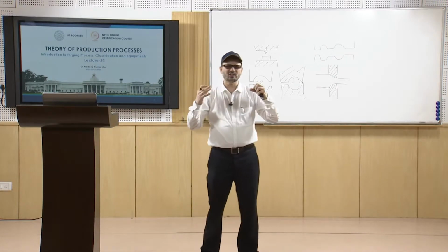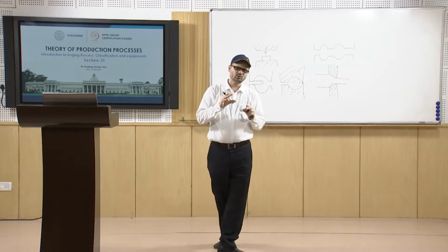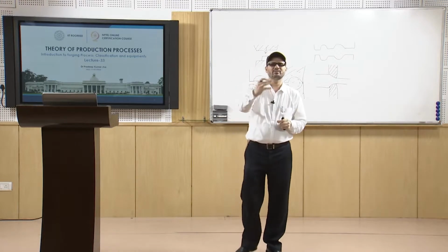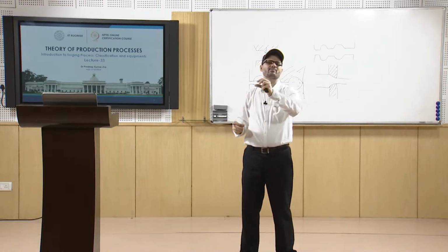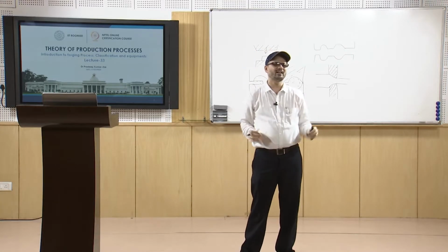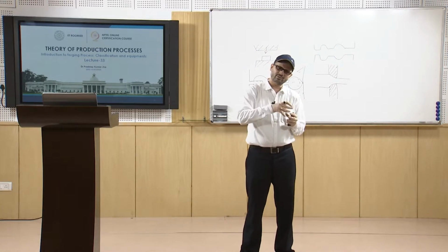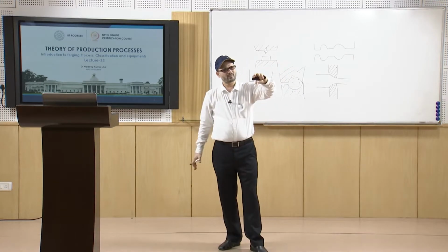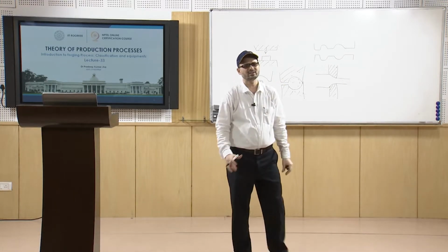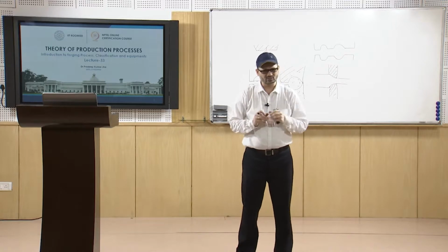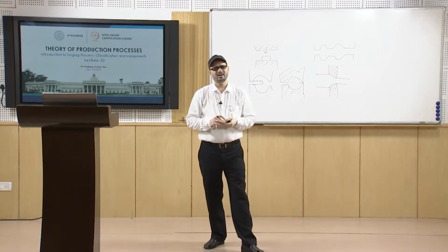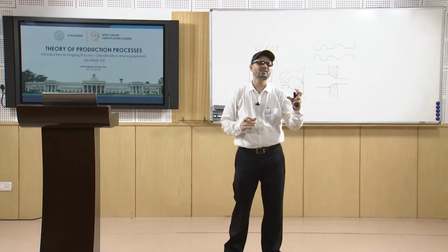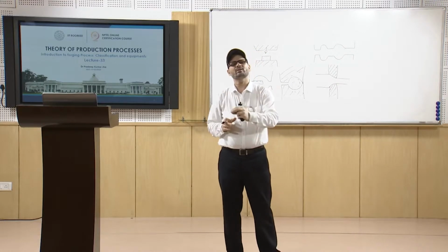The initial purpose is, depending upon the cavity and wherever you require larger material or lesser thickness, to first arrange the metal in such a way that wherever you have large thickness, more metal goes, and wherever you have less thickness, less metal goes. Then you have to see that proper corner radius is given, so that there is proper flow of material into the cavities.